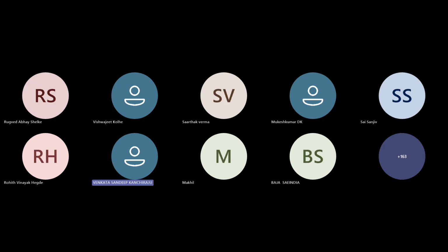How can MATLAB be used for other than the brake model? MATLAB can be used to configure your powertrain modules. If you are using a CVT or a manual gearbox with the electric configurations, then you can configure your vehicle in MATLAB and import it into CarMaker.